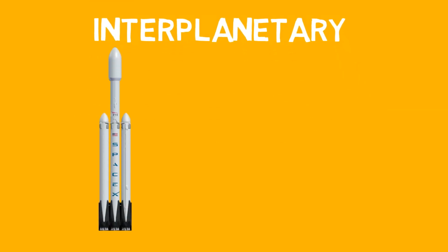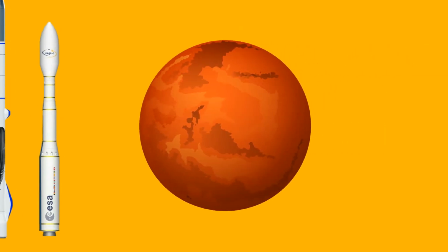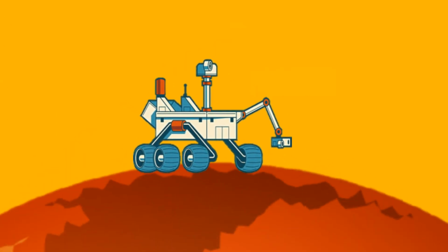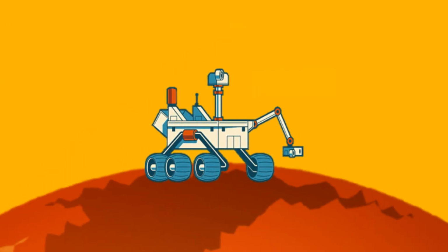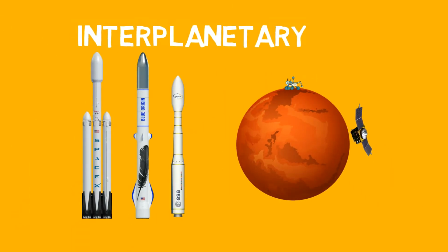Number 4. Interplanetary. An interplanetary spacecraft spends most of its flight time moving under the gravitational influence of the Sun. Interplanetary flights are commonly launched with the vehicle's final stage into a temporary parking orbit, to allow spacecraft checkout and more precise control of the final injection maneuver, rather than being launched directly to terminal velocity. Then with the gravitational assist of bodies such as the Moon, Sun, or planets, the flight is slingshot into a path to reach the planet with a very high velocity.